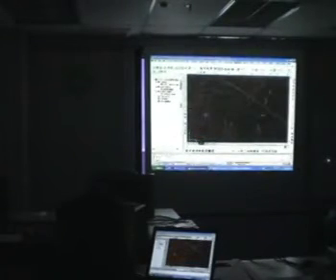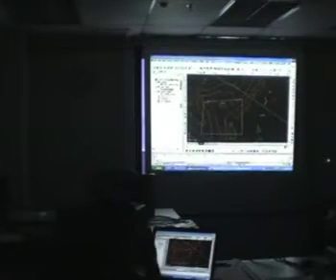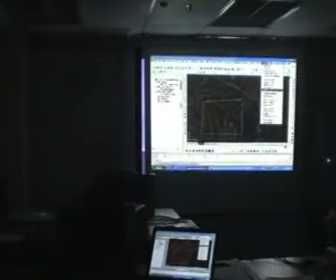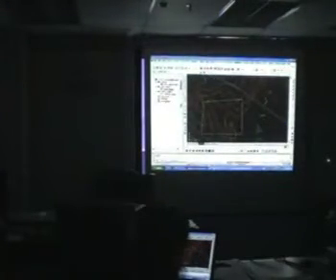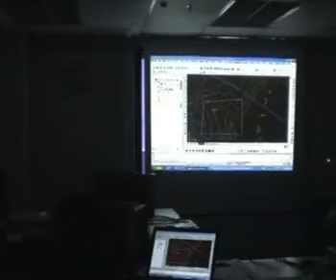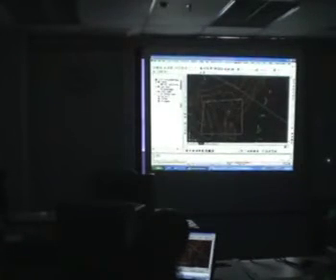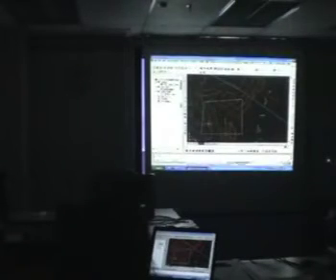I'm going to zoom into this blank spot. Okay. And I'm just going to draw a platform here. Not sure what level this should be. So let's say I just want to check what is the elevation of my existing ground. There is a very unique function here called track elevation, which you look at the bottom here, instead of coordinates now, it's been changed to ELEV, elevation. And just by moving my cursor, you can see how the number changes. That indicates the elevation of the original ground level at where my cursor is. Okay, so now we see it's about 30 odd, 40 something. Okay, so I'm going to put this platform perhaps at 35.